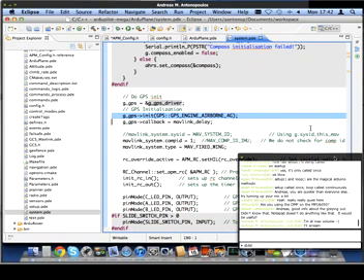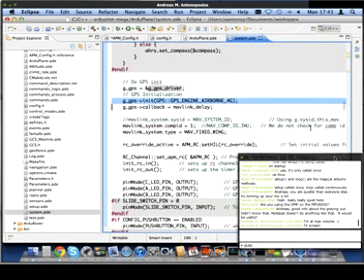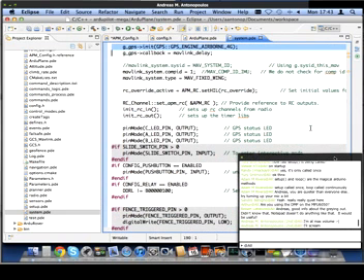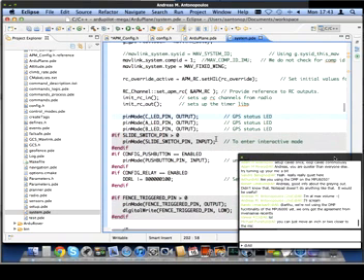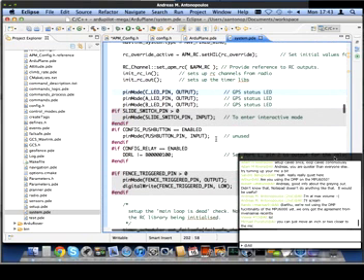That changes the filter inside the GPS for how to optimize the GPS output for the type of movements you expect. We pass in different numbers on ArduCopter and on APM rover, because a rover is unlikely to be pulling a 4G aerial turn, and a copter tends to pull less sharp turns, so it can filter more accurately by setting up different parameters inside the GPS.